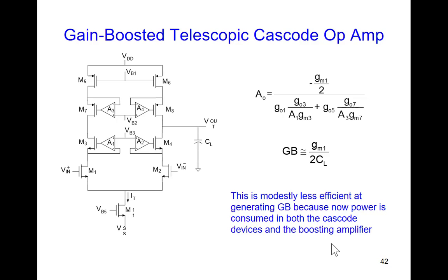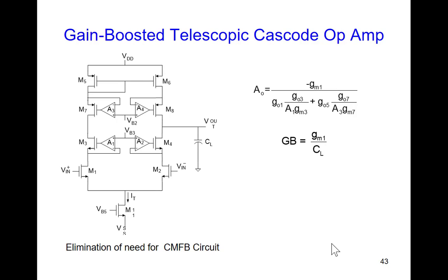And most of the other amplifiers we're going to look at are going to have more gain or more signal swing. We know what the signal swing here is. We don't need much signal swing on this node. And I don't know that we need more gain. I mean, when we go to the regulated cascode structure, we're already up in the 100 to 120 dB gain range on our op amp. There aren't many applications in the world that require op amps that have a gain bigger than this. So what advantage would we have of putting in a bigger A amplifier? Well, if the gain of the amplifier was bigger, we get more gain of our overall amplifier. But at some point you say that's good enough. Does that make sense? We're getting really high gain.